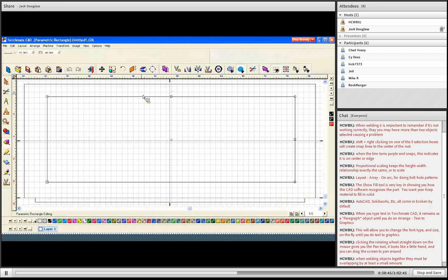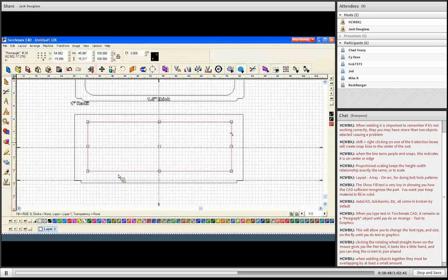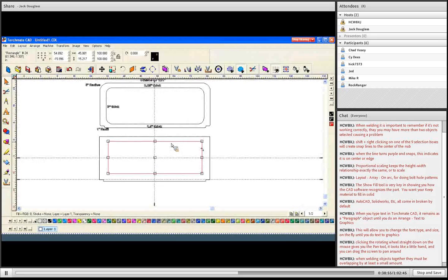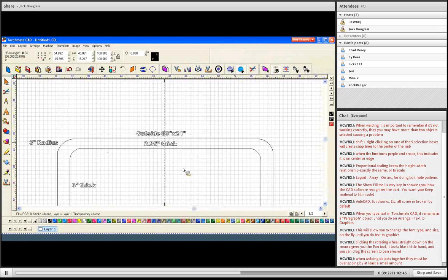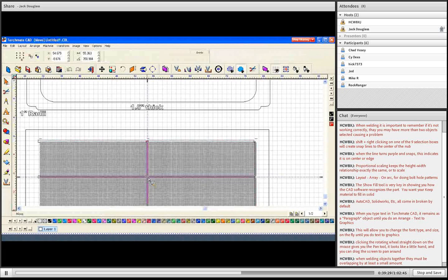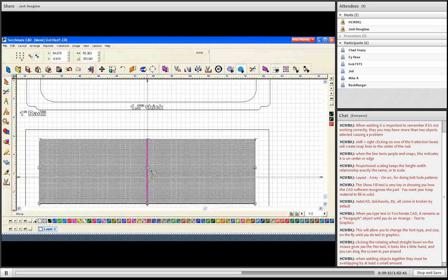And again, originally the size doesn't matter. We'll change it right now. So our overall dimensions were 53 by 21. And this part, from the top here, was supposed to come down 2.25. It's supposed to come up 1.5, and it's supposed to be 3 inches in on each side. So it's centered horizontally, but not vertically. And so the first thing we would do is just set our width as 3 inches, so 6 inches less than our outside of 53. So that would end up being 47. So for the width, I'll type in 47. And know that that's going to at least center up this way.